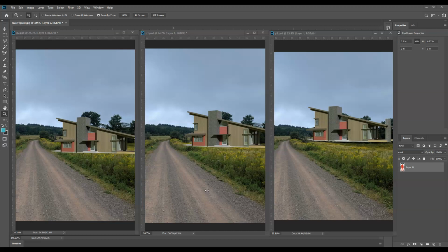When you work like this, you actually work backwards, because the 3D modeling software has already given you a set of perspectives with horizon line, vanishing points, and all of those things. And the photograph you've taken of the site already has inherent to it horizon lines, vanishing points, and all of those sorts of things. And so it's easy to skip that step, merge them together, and do it incorrectly. The reality is what you have is a drawing, and you have to reverse engineer it and find, particularly, the horizon line, because in any image there's only one horizon line, and all horizon lines between all the elements must match.